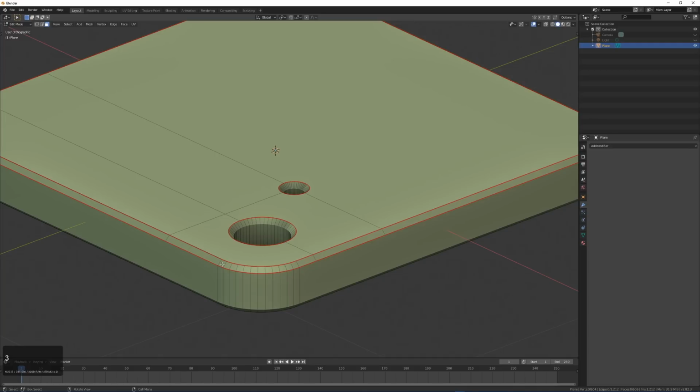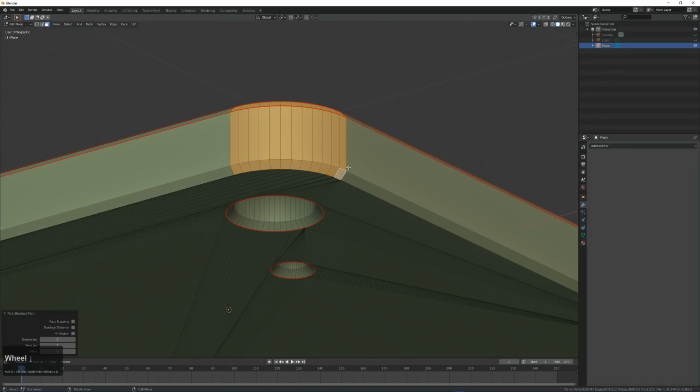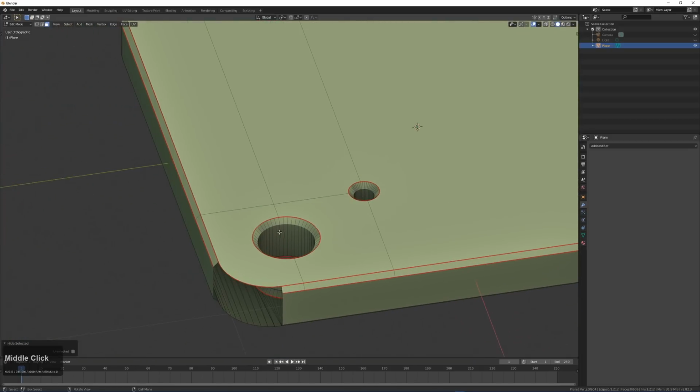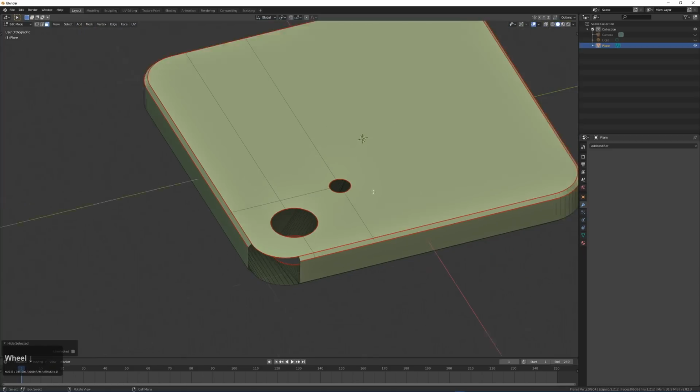So another useful tip is we can select a face, and by holding Control, you can select from one face all the way to another one. So I'm just going to select that one, hold Control, select all the way there, and do it on all sides here, and just hide that. We'll press 3 to go into face mode, and because we marked these with seams, not for UV purposes, but to press L and select just that linked geometry and hide it.